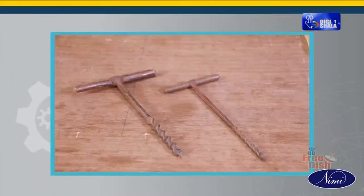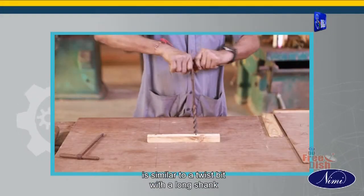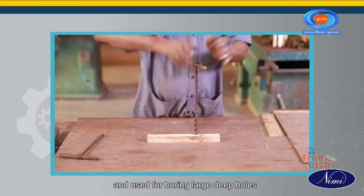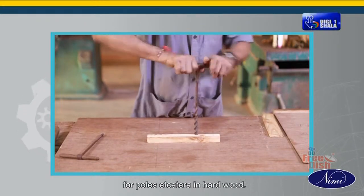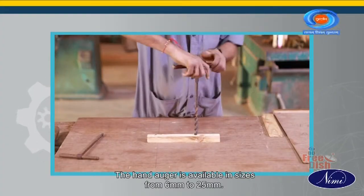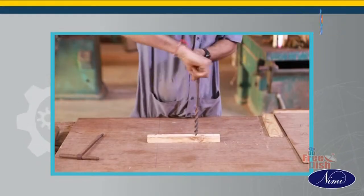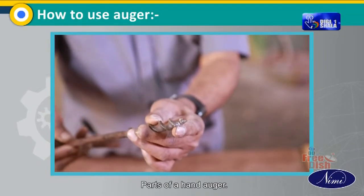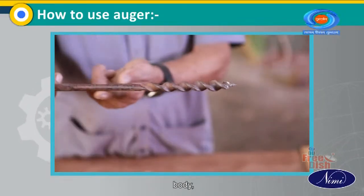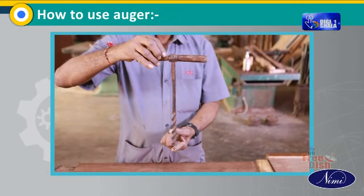Let's start. A hand auger with a twisted shank and threaded point is similar to a twist bit with a long shank and used for boring large deep holes for poles, etc. in hardwood. The hand auger is available in sizes from 6 mm to 25 mm. Parts of a hand auger: point, shank, eye hole, body, handle. Let's see each of them in detail.